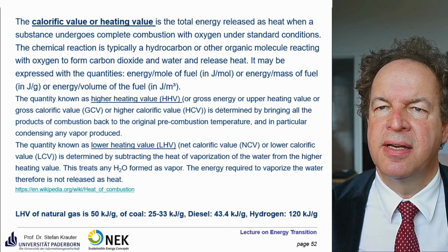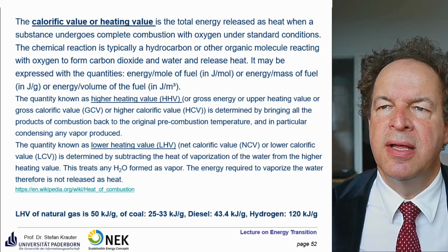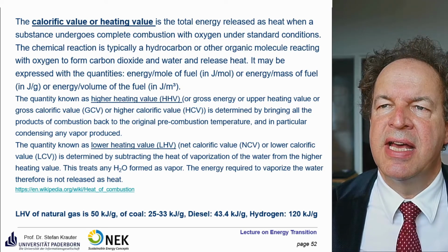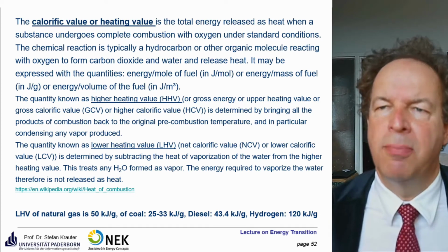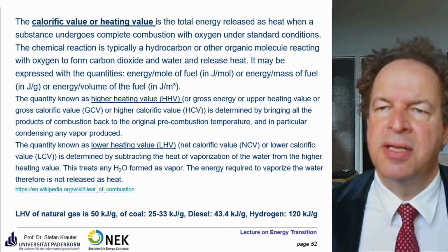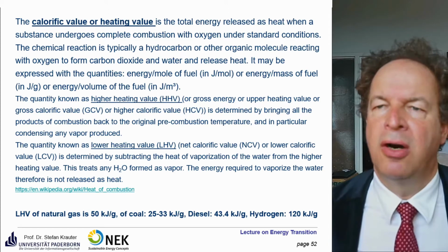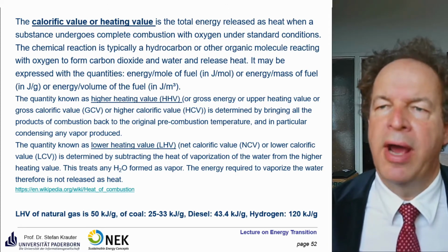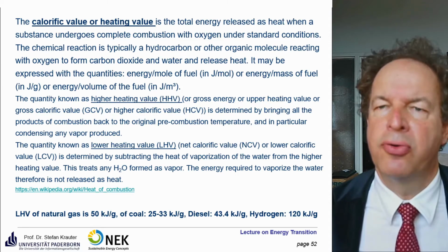Also quite important is the calorific value or heating value. That's the total energy released as heat when a substance undergoes complete combustion with oxygen under standard conditions. The chemical reaction is typically a hydrocarbon or any other organic molecule reacting with oxygen to form carbon dioxide and water. It may be expressed in quantities of energy per mole of fuel, so joule per mole, or energy per mass, so joule per gram, or energy per volume. For example, if you have gases, joule per cubic meter.